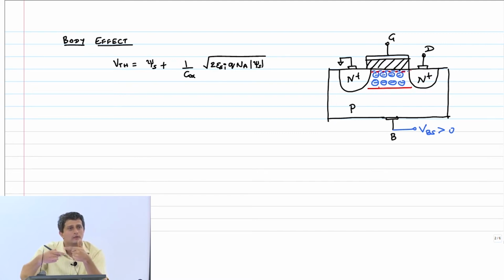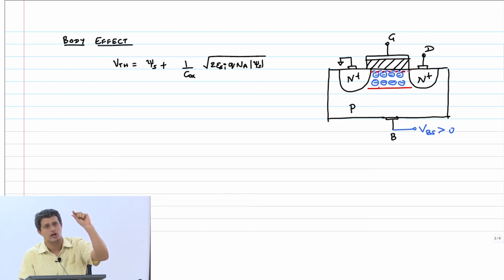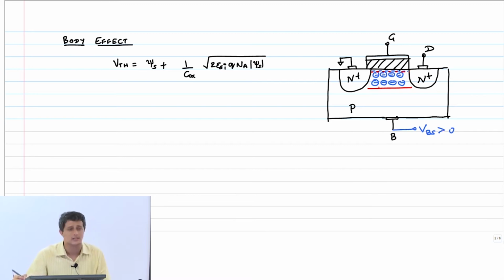is going to act like a back gate capacitor, just like the silicon dioxide on top provided control for the gate. This capacitor behind here is providing some control to the channel, and that can be controlled by the body terminal. So just like we said, if gate potential goes positive, you start getting some negative charges at the channel, a similar thing will happen here. This is again only an abstraction, it's not a physical picture. So you can treat this like a back gate, and therefore if VBS is greater than 0, I will already get some negative charges.